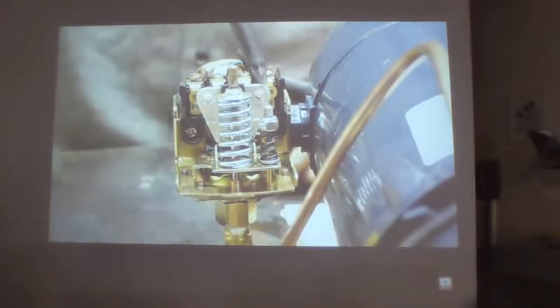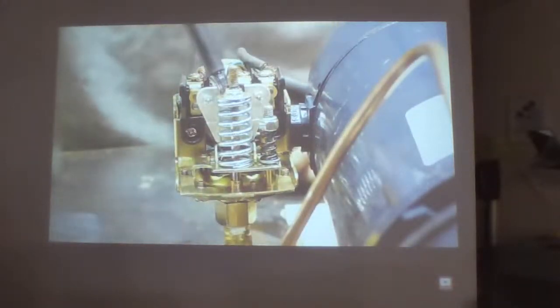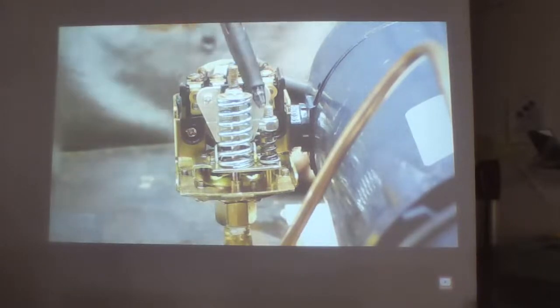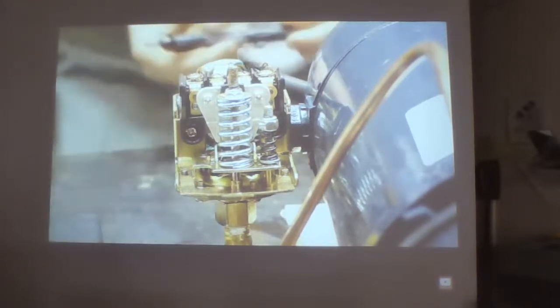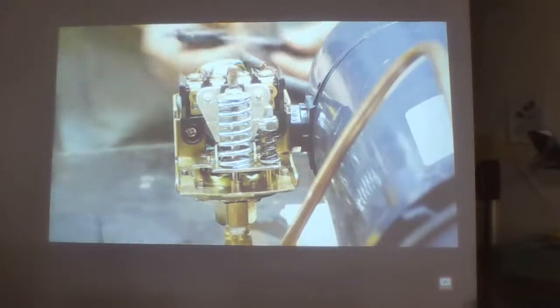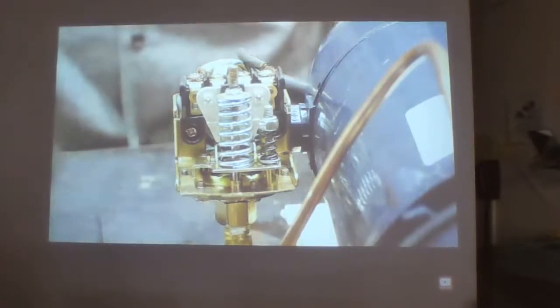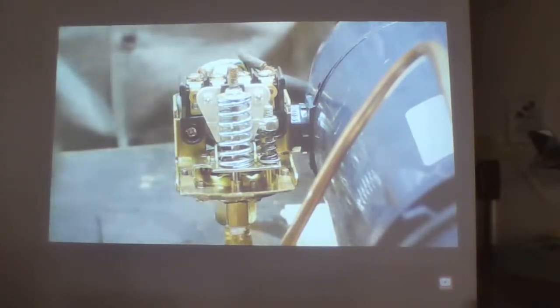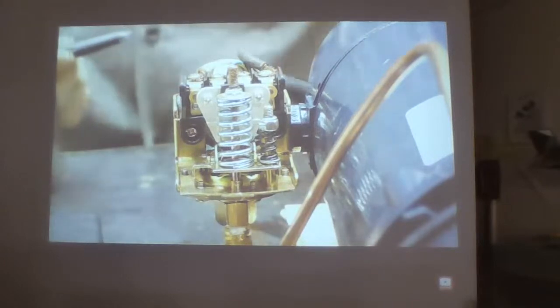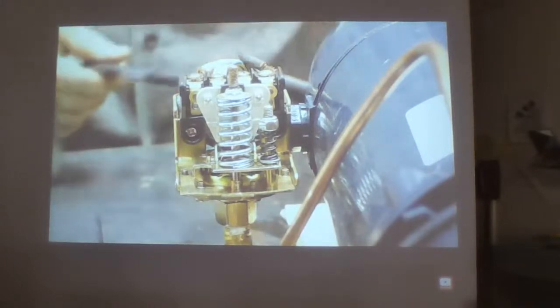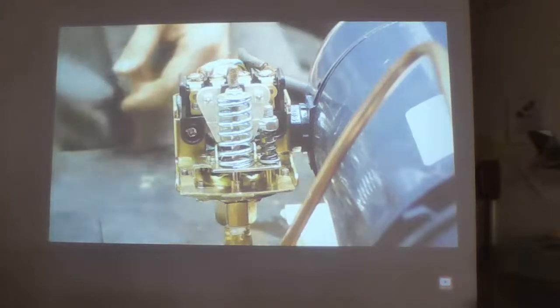So with this particular one, it's a lot less adjustable than the large one. And a lot of pressure switches have a range that this will work. Sometimes it's 5, 10, or 15 PSI, depending on the switch. Let's go ahead and run this pump through a cycle so you can see how the pressure switch operates. And we'll also see what's going on with the pressure gauge.